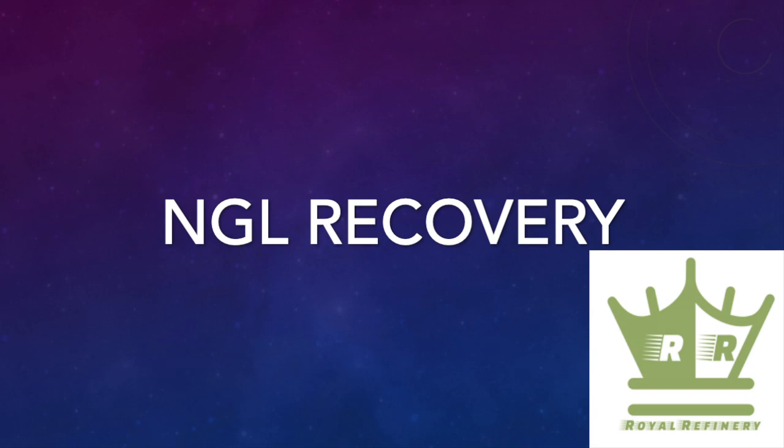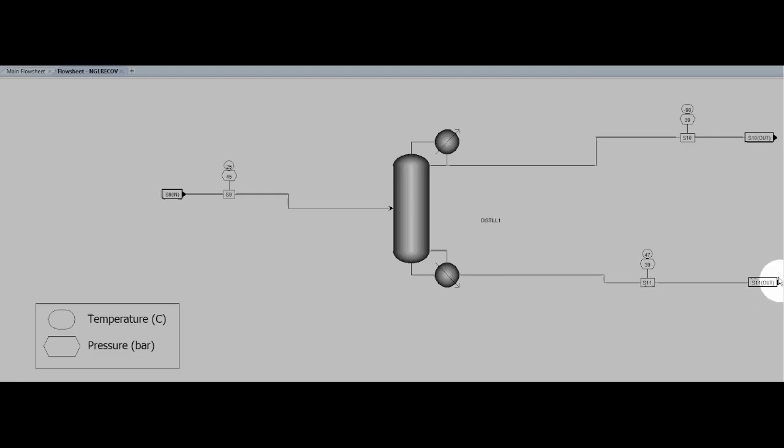NGL recovery. This step involves the removal of hydrocarbons heavier than methane from the feedstock using cryogenic distillation and turbo expanders to ensure high purity methane. The column has a distillate temperature of -90 degrees Celsius and a bottom temperature of 47 degrees Celsius. The column pressure is 39 bar. Peng-Robinson was chosen as a thermodynamic model for this section as it allows for a good correlation for non-polar systems encountered in the petroleum industry. A shortcut distillation column, DSTWU, was used for this step as it provides a good separation.